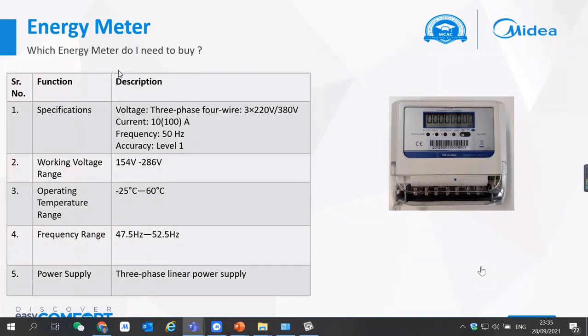The converter module is for when you are using the diagnosis software with an old generation outdoor unit like V5X. As I mentioned, V5X used to have K1, K2 and XYE, two ports. And the new generation V6, VC Pro only have XYE.